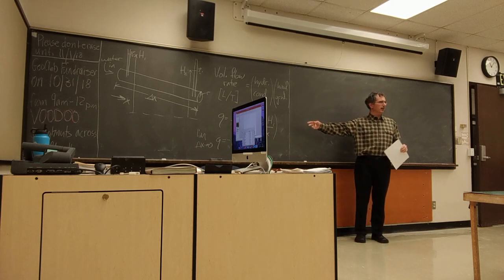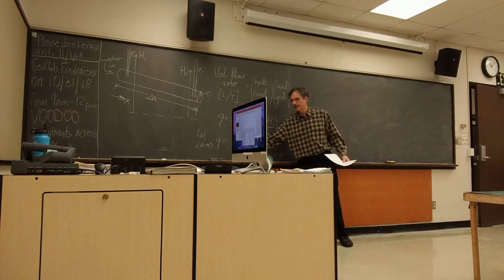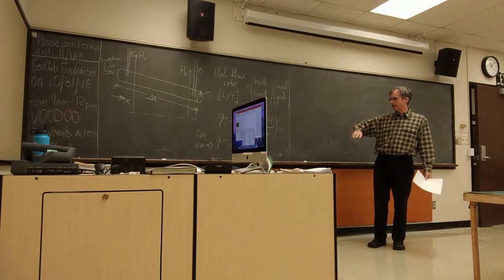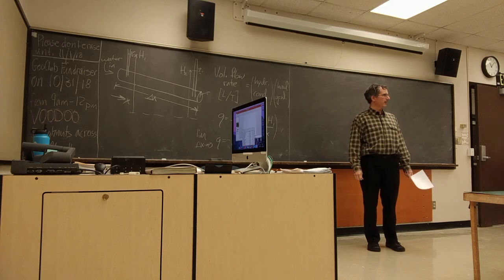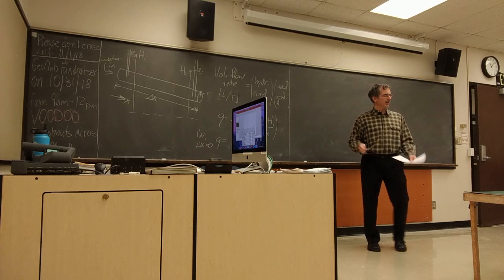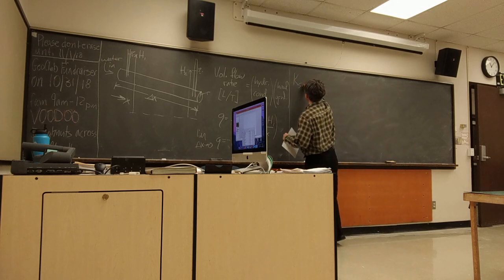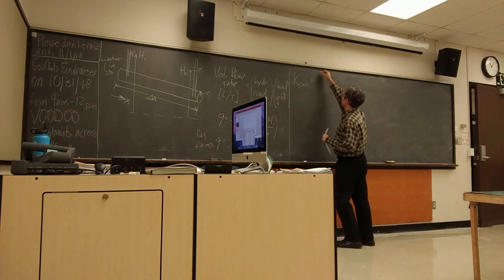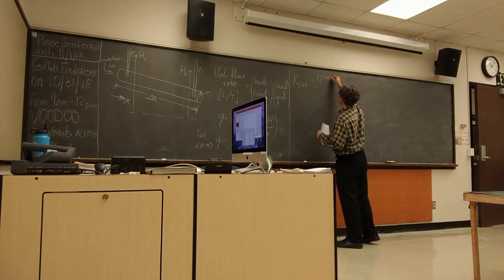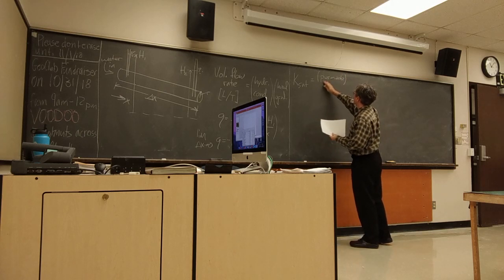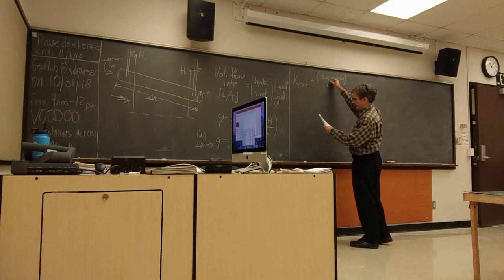What's in the saturated hydraulic conductivity? I keep being a bit anal about putting a sat on it, and I'll get to that in a bit. But what is that K-sat? Well, it combines permeability, which is, of course, a material property, has units of length squared.